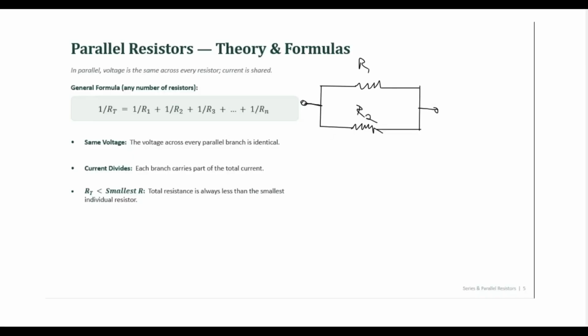So any current that is coming into this configuration is going to be divided among these resistors. And you can have any number of resistors in parallel. So irrespective of how they are arranged in a circuit or how they appear on your diagram, once they share current, they are in parallel. That's the secret to decoding resistors in series and in parallel, because sometimes the way your circuit diagram appears might be a little bit confusing.